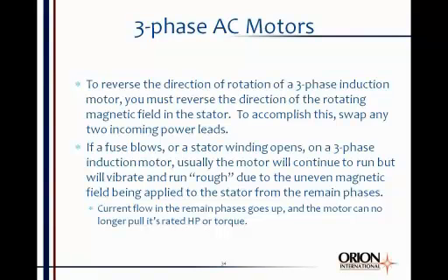The motor will oftentimes continue to run, it'll vibrate, it'll run rough, and it can't operate at anywhere near its full rated horsepower and torque. The current flow in the remaining phases goes up. Sometimes that'll cause another fuse to blow, and then the motor will stop running.